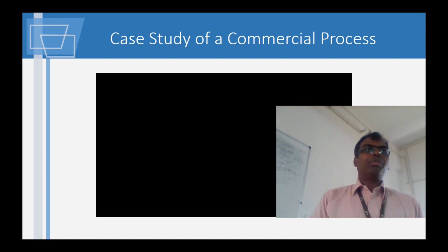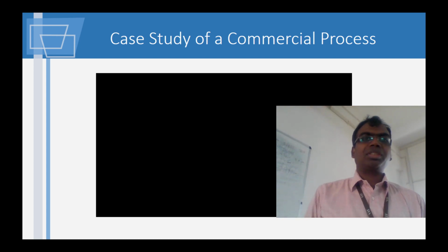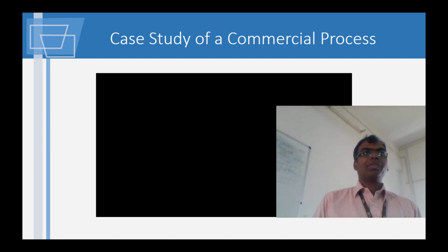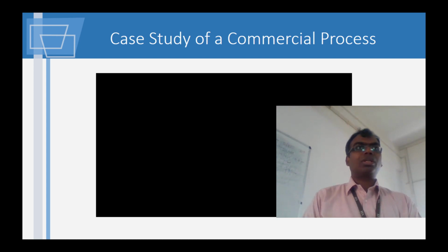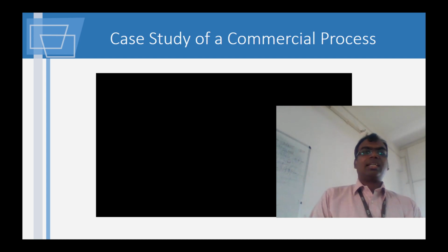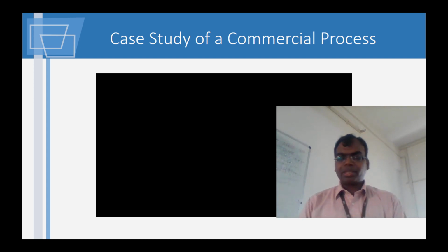process might not be very successful in all places, because if it's very cold and all that, the microorganisms will not be as effective as the other things. So this also applies to trickling filter, and in many of the cold countries they are actually banned. And in one of the subsequent videos, a person is trying to make the system viable for even cold places, because this is very good and very effective.